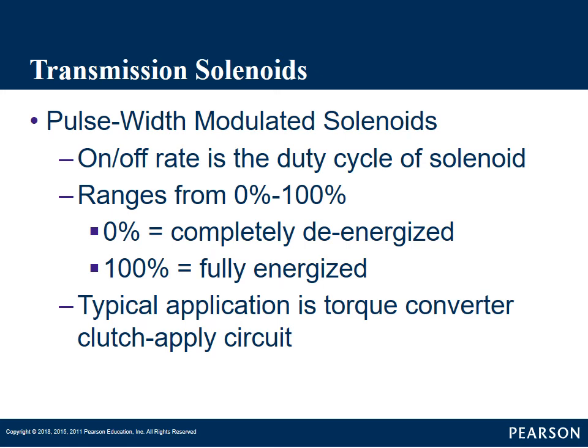That's our duty cycle, or pulse width. We see it in injectors. We see it in some of our fuel pumps on some fuel systems. On a pulse width modulated solenoid, how long they keep it energized is our duty cycle. So they can change the duty cycle to gradually apply something or gradually control the pressure. It's not just on and off.